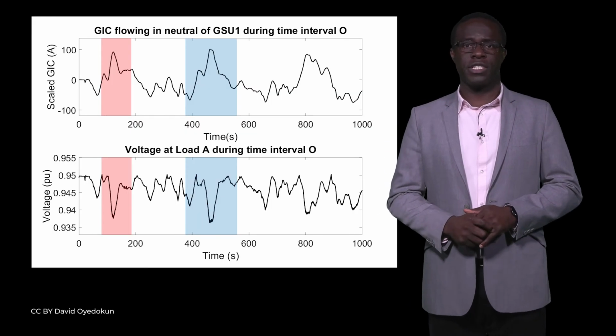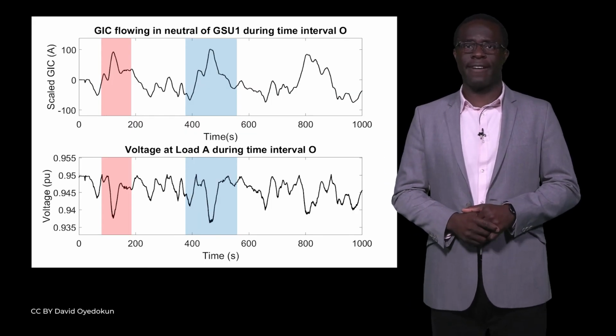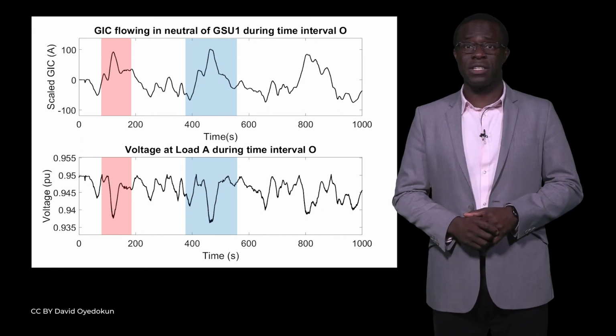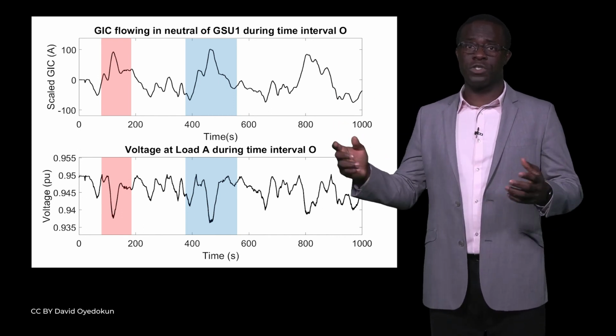During the main phase of the storm, the dominant frequencies were low. The slow variation in the GIC causes a relatively slow voltage decline. The three peaks in the GIC profile clearly show that Pc5 pulsations were driving significant GICs, leading to sharp voltage drops.